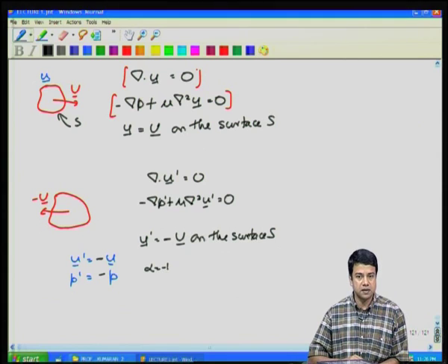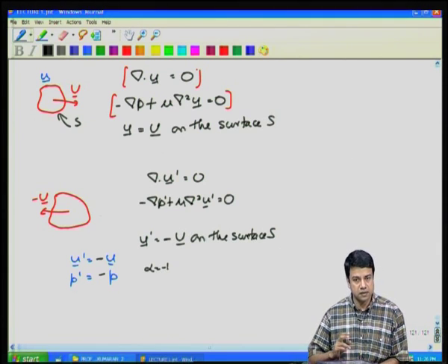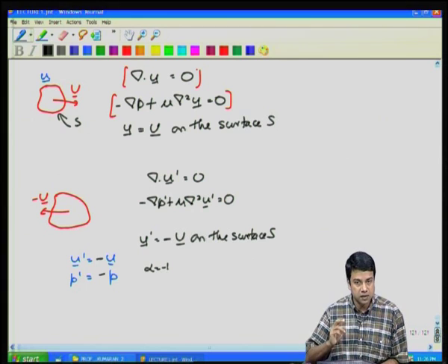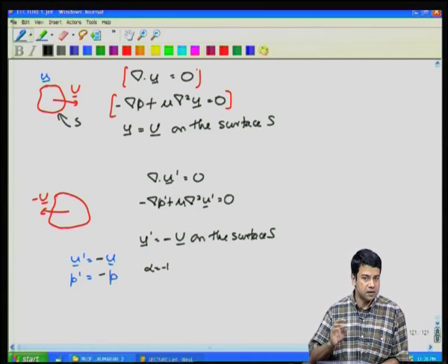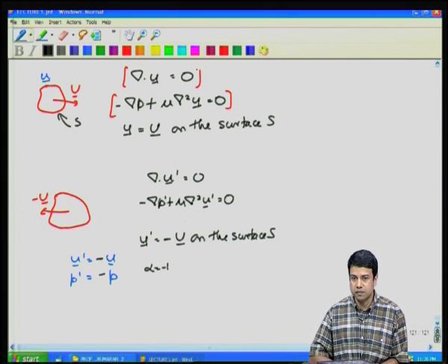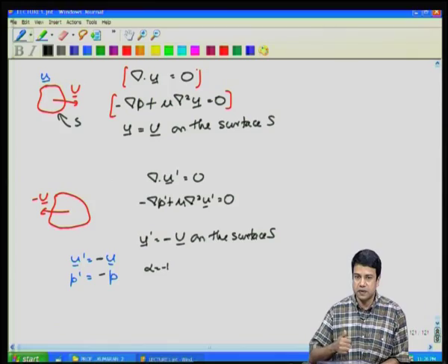So, if the stress is doubled, that is, you increase the mass 2 times while keeping the shape of the object the same, then the velocity as well as the stress and the pressure at each point is doubled. If the direction of the stress is reversed on the object, then the velocity, the pressure and the stress at each point are exactly reversed. So, that is a consequence of linearity. And this leads to things that we would not intuitively expect based upon our experience with macroscopic flows.